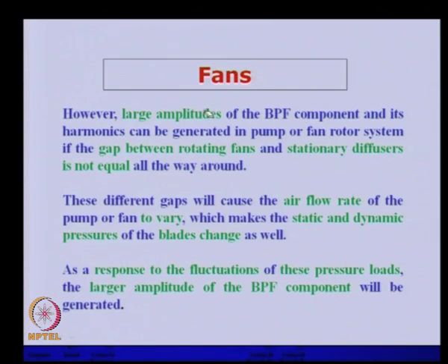However, large amplitudes of the BPF component and its harmonics can be generated in pump or fan rotor systems if the gap between the rotating fan and the stationary diffuser is not equal all the way round.